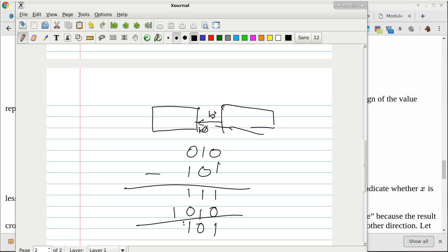So when we look at the sign bit, it is not telling me the truth, because -2 is not less than -3, and yet the sign tells me the difference is negative. That's why we have a problem. But we can fix that problem. If I can tell when the difference is overflowing, then I can combine that result with the actual sign bit and come to the conclusion correctly.